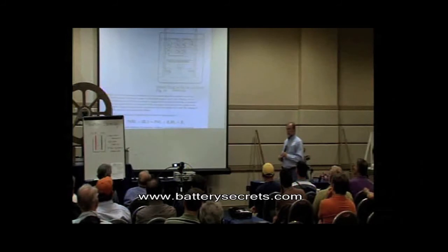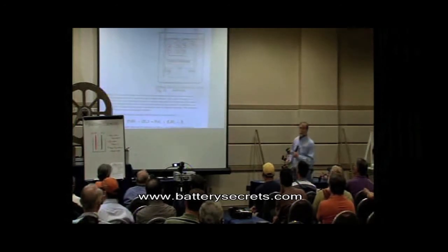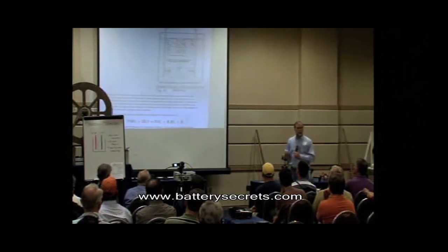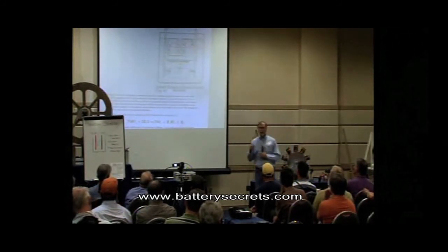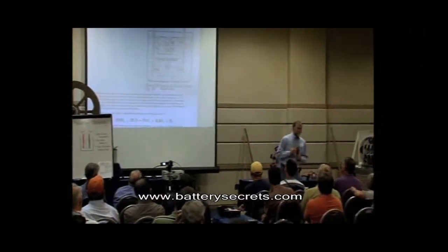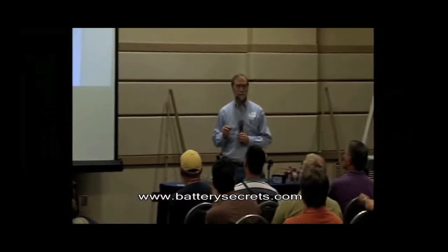If you aren't doing that, then you're not charging the battery. And what happens is that when this is done insufficiently so that this bond is really well established, this material starts dropping. It may form, but if it doesn't form in such a way that it actually plates to the plate, it will fall to the bottom. And at that point, it is disconnected from the electrical circuit and becomes an inert sludge at the bottom of the bucket. Does that harm our battery?